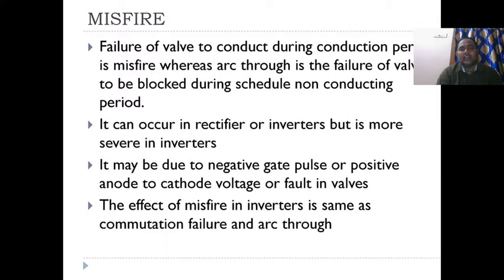Next one is a misfire. The name indicates there is a misfire. Arc back and arc through. Arc back in rectifier side, arc through in inverter side. The misfire occurs on both sides, in the rectifier side as well as the inverter side.